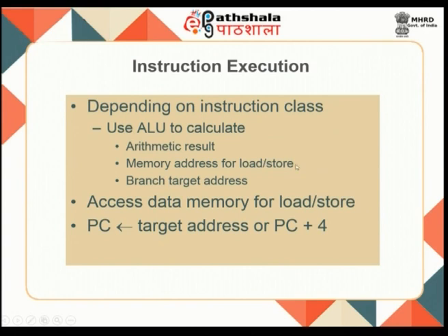Now, once you do all this, the fourth step is accessing data memory for load and store. Now, this step is actually necessary only for memory related instructions, which is load and store. All other instructions will never perform a memory related operation.